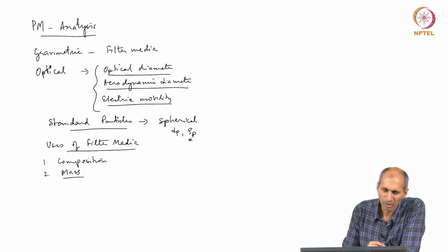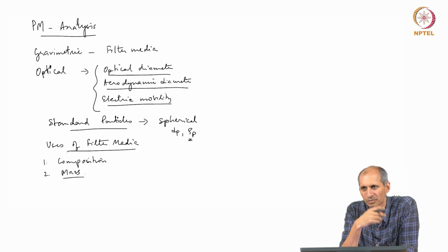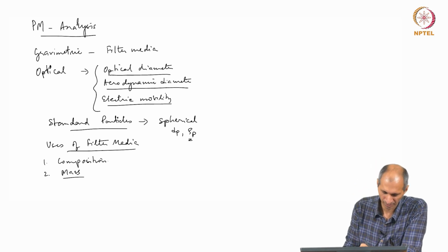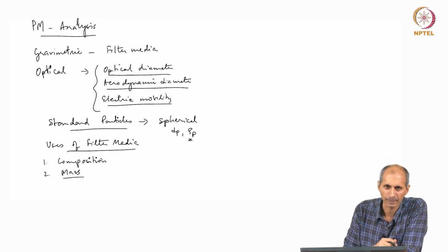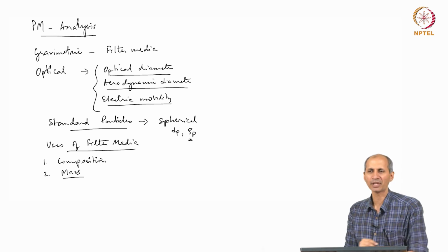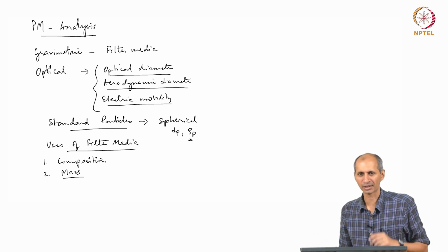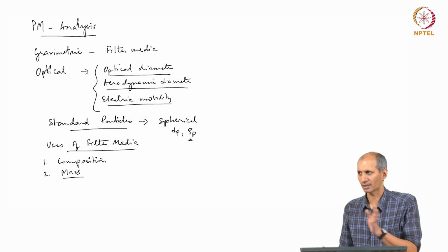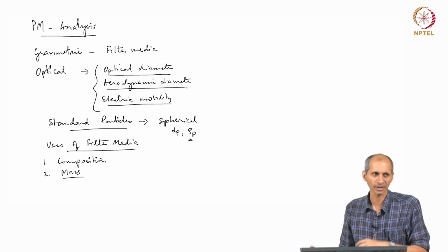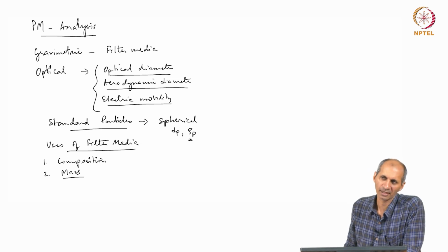But as we go deeper into the problem, these mass-based detectors have severe limitations, and we would like to understand more about the physical processes happening in the environment. We would like to have more real-time and distribution-based instruments. So you can imagine if I use an SMPS, which is the DMA and the CPC that we discussed, how much information can you get if you sample for one day at a roadside? You can get tons of information, you can do data analysis on that, all kinds of inferences can be made.